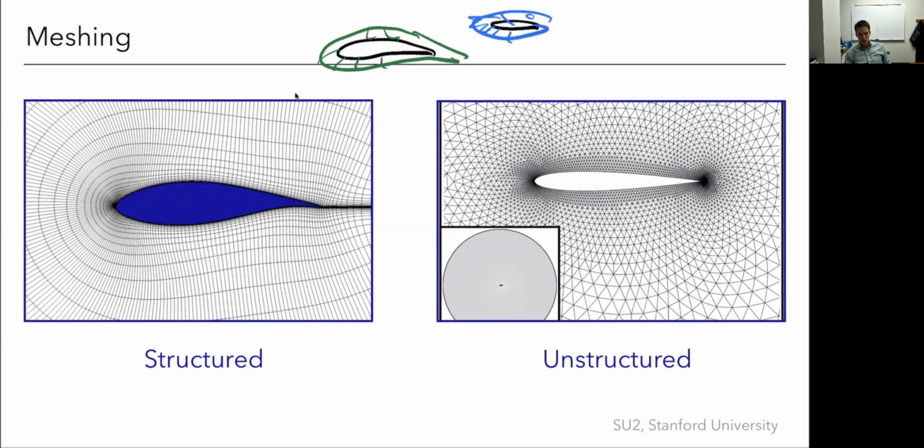And so an unstructured grid doesn't rely on the structure. And they're very general methods, I can mesh around arbitrarily complex bodies. So this is kind of the most common technique, is that we use a structured one near body. There are reasons for this. As we talk about later in the semester, viscous flow, we find that things change very quickly normal to surface, but very slowly along the surface.